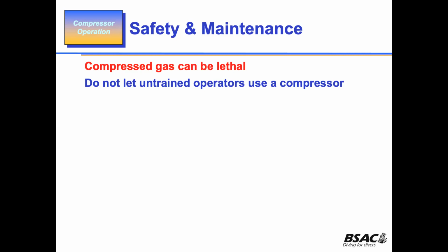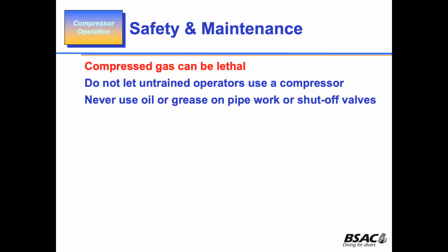Don't throw them around, right? Because remember, if you damage that valve and that valve comes out, you've got 200 bar coming out, whoosh, like a rocket engine, and it will propel that cylinder. And if you're in front of it, you're not going to be alive. Sorry, it's as easy as that. So don't let people who don't understand use the compressor.